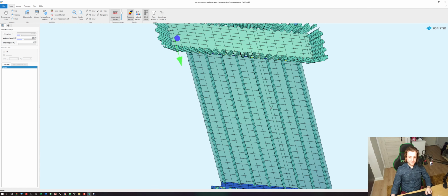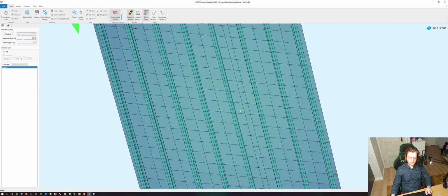Okay. And also we want to have full control of the division of these two parts. Usually I made them as single divided elements, and also this one always I made a single divided, because there is no need to divide it in more elements, since this element is already quite narrow.